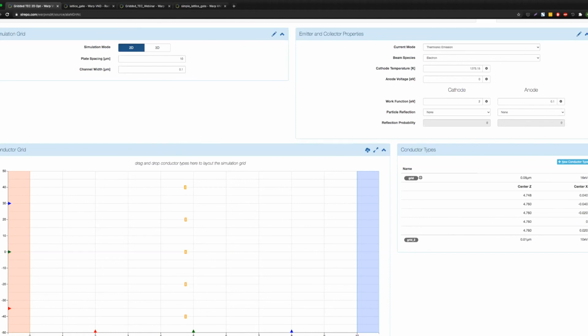And so oftentimes what they use is a combination of supporting structures, basically small-scale cylinders made of some kind of insulating material that connect the emitter and collector. Then they'll use an additional set of electrodes connected to those cylinders to accelerate particles to compensate for space charge. If you can make the gap small enough, then in principle you won't have to worry about space charge. But in practice, it's not done very commonly. I think there are a lot of modern designs aiming to do that, but I don't think they're fully mature yet.